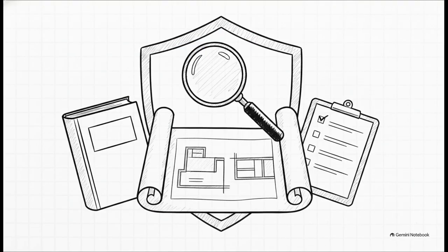Your administrative prep is literally your first line of defense. Before you even think about picking up a tool, you've got to read and interpret your work instructions. These combine info from the plans, the clients, and specific safety procedures for your role. You have to comb through those plans, specs, and drawings so you know the exact circumstances where asbestos might be hiding on your specific site. Plus, you need to plan your tasks to strictly comply with legislation, the National Construction Code, and workplace health and safety guidelines, all while nailing down the precise quality requirements for the job at hand. It's a lot, but it is absolutely essential.